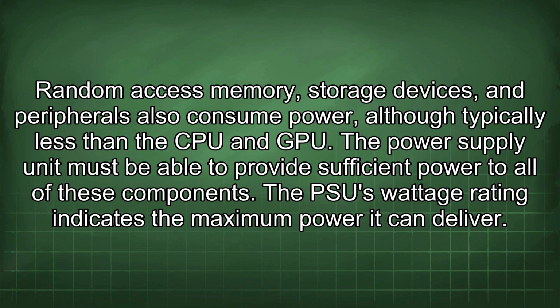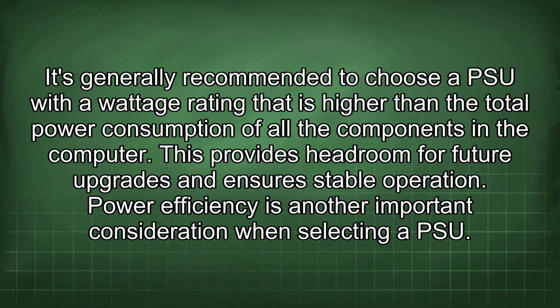The PSU wattage rating indicates the maximum power it can deliver. It's generally recommended to choose a PSU with a wattage rating that is higher than the total power consumption of all the components in the computer. This provides headroom for future upgrades and ensures stable operation.